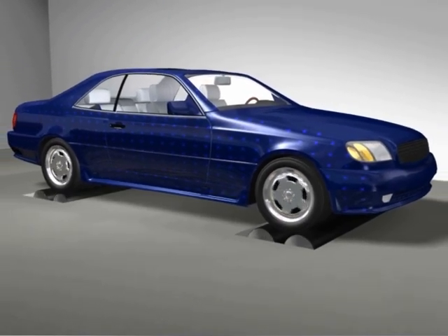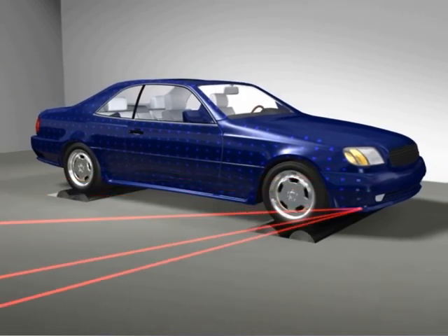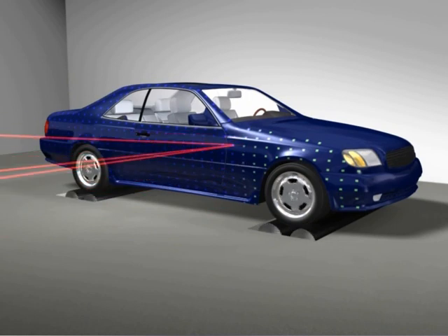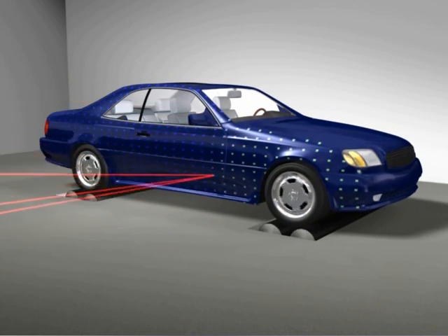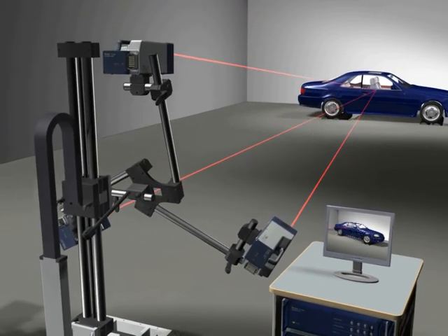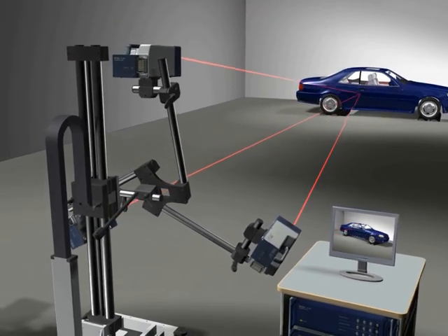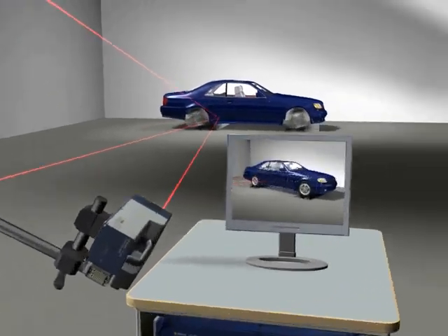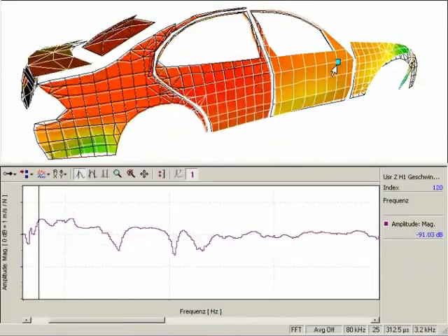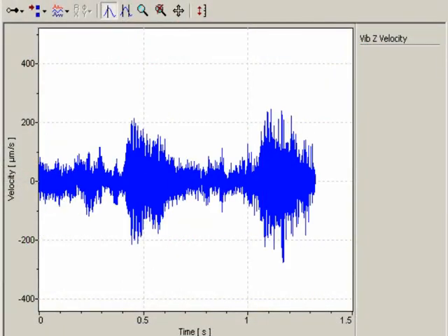The 3D scanning laser vibrometer uses light as the sensor, eliminating the influence of a traditional contact transducer on the test object motion. By using scanning mirrors, the light is sequentially placed on a grid of points, measuring the motion of a complete surface. Three measurement heads sample each grid point in three separate directions, uniquely determining the vector motion at that point. Vibrometers deliver meaningful results.